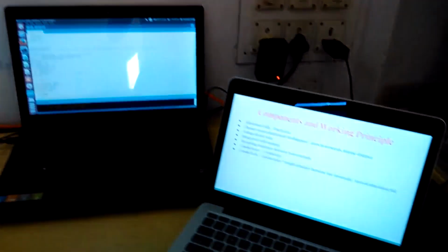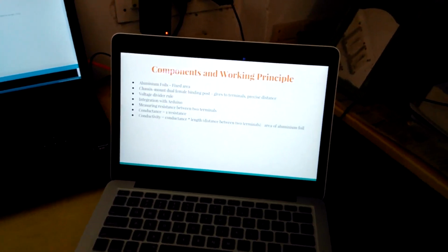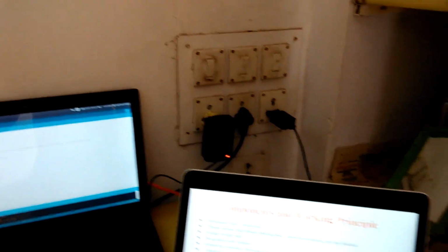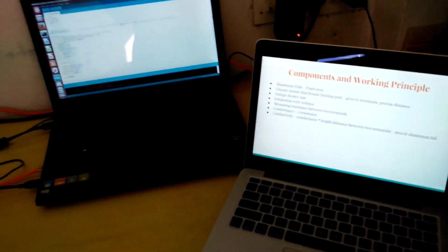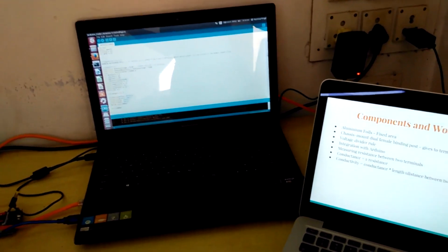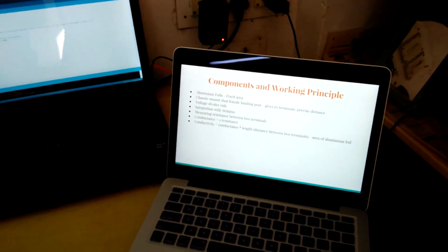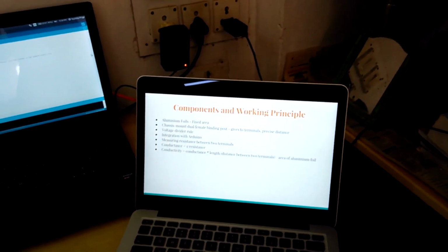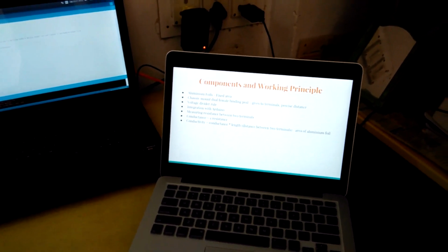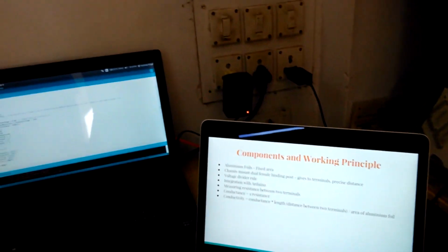And interestingly, we do not need a separate sensor or circuitry to find out the total dissolved salts. There is a simple relation. If you multiply 0.67 into the conductivity in proper SI units, it gives you an approximate idea of the dissolved salt content in water.